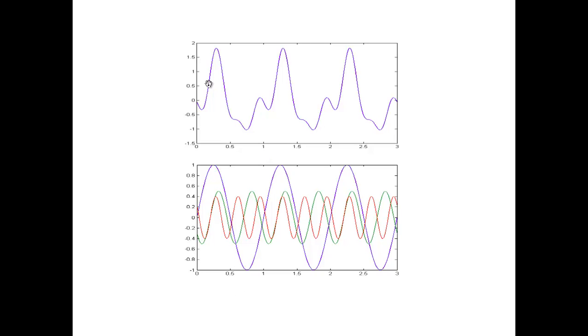And so now, rather than thinking of this weird shape and trying to figure out what that bump means there, it turns out that doing it that way is not going to help you understand what this sounds like, because I can get 2 sounds that sound the same to you and look very different. So that's not the right way to go about it. But the magnitudes and phases, this interpretation actually does tell you a lot about how it's going to sound. This would be a way of analyzing the signal if you first dissect it into sinusoidal components. That gives you a way of identifying what the sound is like, where you could automatically say, "Oh yeah, this came from a saxophone," or "This is the sound, the vowel."